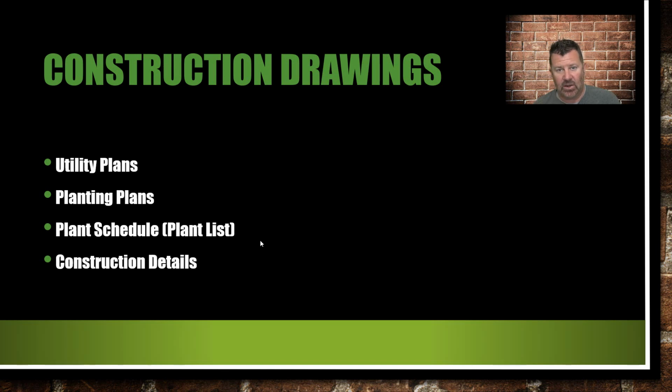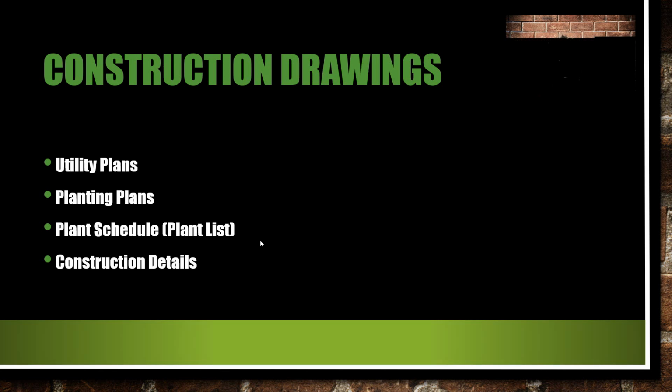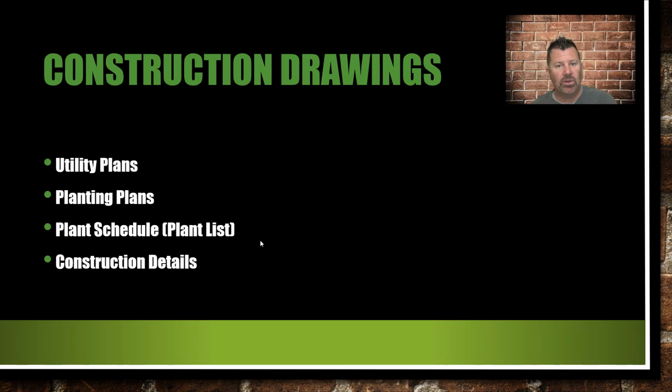Guys, I take a highlighter, and if it says 10 crepe myrtles, I'm going to highlight each one that I count. 1, 2, 3, 4, 5, 6, 7, 8, 9, 10. Highlight. Ooh, 11. There's an extra LI or Lagerstroemia indica on the plan that's not listed in the plant schedule. Oops. You got to go back to the nursery and get one, don't you? Because the plans is what you got to go by, not the numbers in the schedule over there. They had a typo. They didn't count one themselves, so you got to do it.